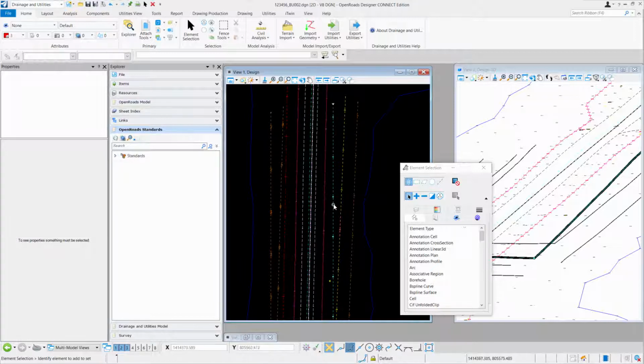So now, why would you use the selection method versus the filter method? So the selection method is going to let you set the size, set the depth for you, whereas the filter option is just taking defaults, but the filter option lets you extract pretty much all of them at once, whereas the selection method, it's each type you have to do separately and change the settings. So that is how you extract utilities.